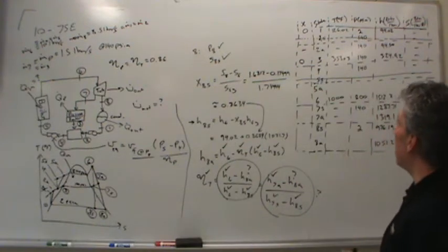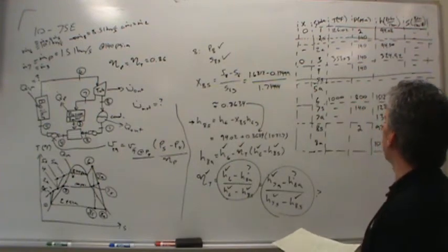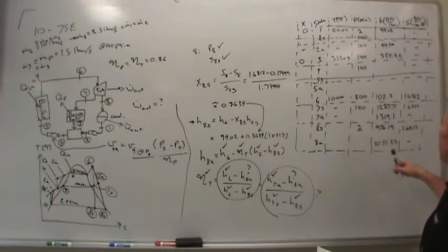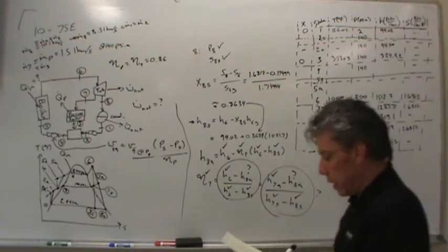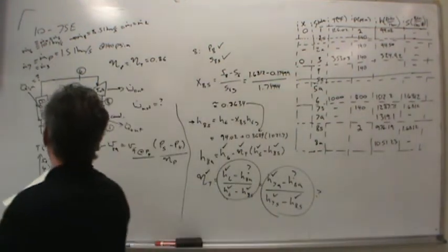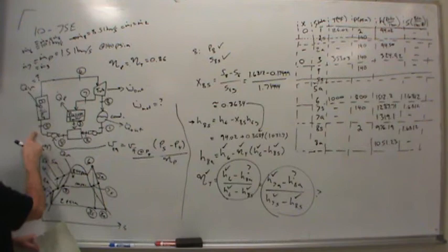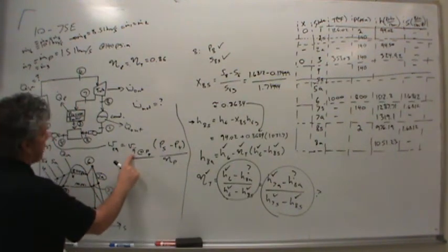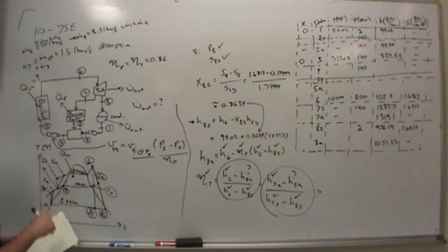Okay, so somehow I have to deal with state 4 and state 5 actual. Those are the two that remain where I need information because those are the two that are missing enthalpies. Now to deal with this, what we have to do is first of all realize that state 4 is the key defining state 5, right? Because state 4 is what we need in order to define the specific volume, and then state 5 will drop out of the specific pump work if we want it to.